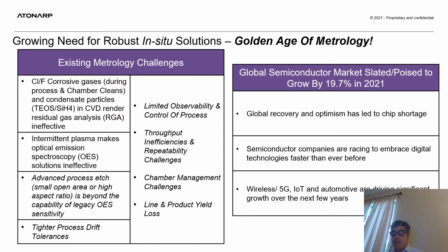Second, OES. Optical emission spectroscopy devices have been used successfully for etch endpoint detection in large node processes. They, however, lack the sensitivity required for small open area percentages and/or high aspect ratio processes, such as the ones used in 3D structures. Furthermore, processes increasingly use pulsed plasma, DIM or remote plasma for radical etching, for instance, preventing OES from providing dynamic chemistry information, namely the consumption of reactants and the onset of byproducts near the wafer.